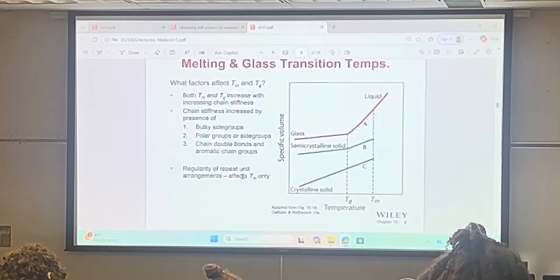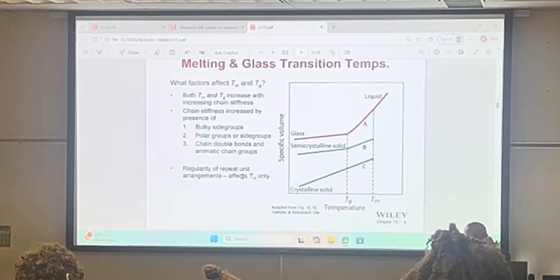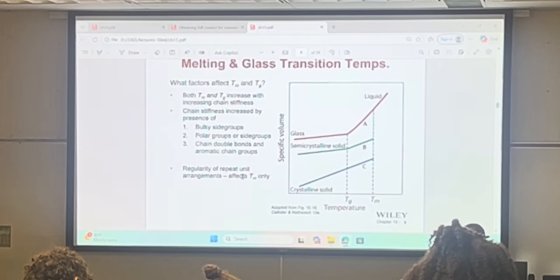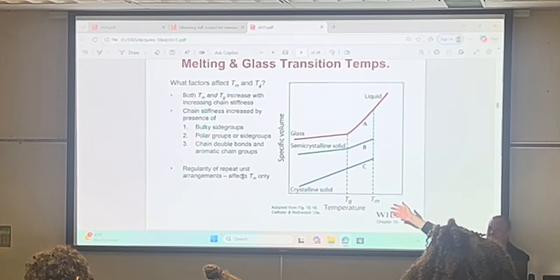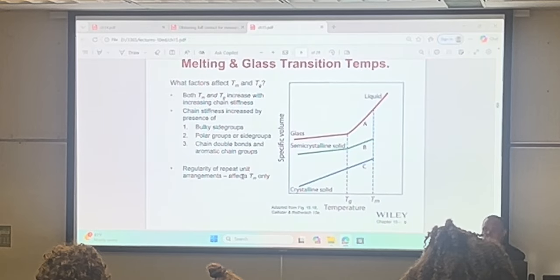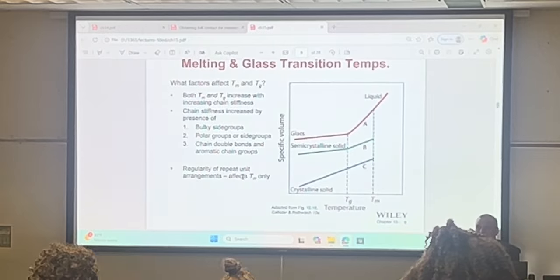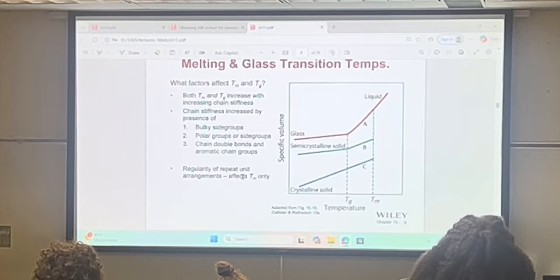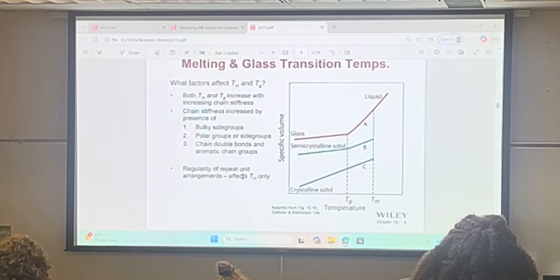They changed the formulation of the plastic. They dropped the glass transition temperature by 20 degrees. So instead of having it at past 150, it started to do the transition at 130. And this package physically bent the silicon chip, so that it stopped performing electrically.